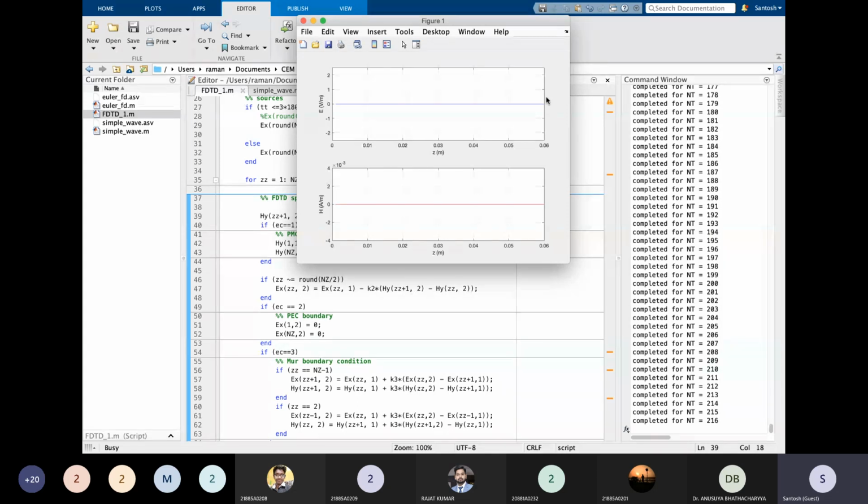One example that you find in circuit theory is this. I don't know if you're familiar with the transmission line theory yet. Some of you are undergraduates, I don't know. So if you have a transmission line that's infinitely long and you want to model it, you don't model an infinitely long transmission line. At some point, you just terminate it with a surge impedance, right? So in that case, the wave goes and doesn't reflect. For a source, it's as if the transmission line is infinitely long. That's what it means, correct? So you could just interrupt me if you are not familiar with this concept.